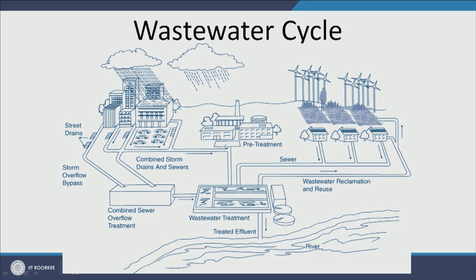Alrighty, in some places like India, we do not have direct collection of wastewater. Instead, what we have is in-house pre-treatment. In in-house pre-treatment, each house or each residential location would have a septic tank. The septic tank will collect the wastewater from the community or from the house, and then it undergoes anaerobic degradation. So, right here we reduce the volume of the wastewater that will go to the wastewater treatment plant, and ideally routinely it should send wastewater to the wastewater treatment plant, but this is advantageous because it reduces the burden on the wastewater treatment plant.